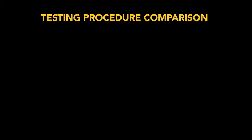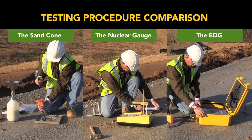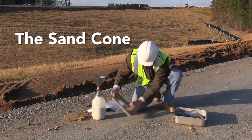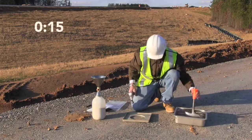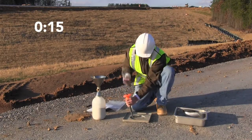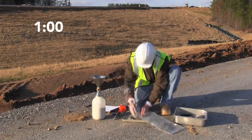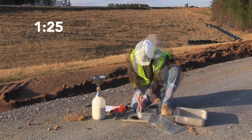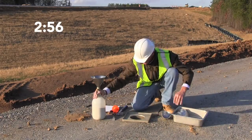To get an idea of how easy it is to use the EDG, let's compare actual testing procedures using the EDG, a nuclear gauge, and a sand cone. First up, the sand cone. Typically, sand cones are prepared in the lab and transported to the site. Here, the technician performs the test and returns the samples to the lab for weighing and a moisture test to be conducted, or the technician can do these tests on site with the use of a scale and a drying oven, which would then yield density and moisture readings. Percent compaction could then be calculated based on Proctor test data.